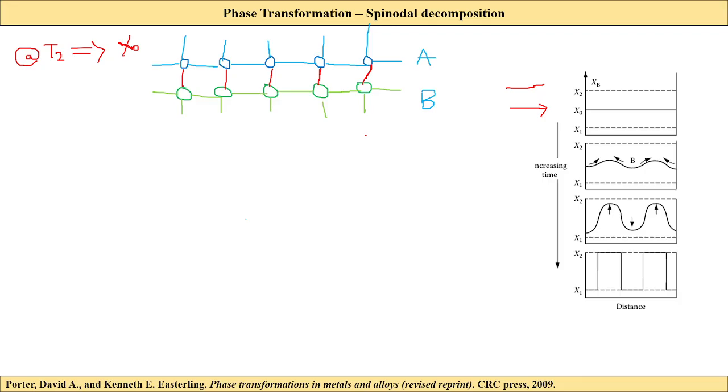Because there is a bond matching between alpha and alpha 2, there is only the interfacial energy. That's all. The grain boundary interfacial energy. There will be no incoherent surface energy, which is quite large when compared to the interfacial energy of alpha and alpha 2. That is incoherency. Right.